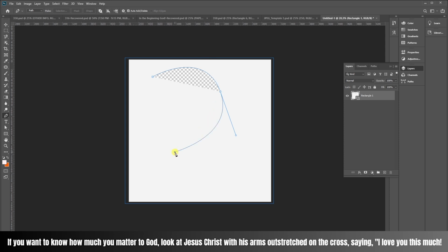Can you see this one is also an arc by default, but in case in the second one I didn't want it to be an arc, what I can do is I press Alt on my keyboard and hold it, and then I click on the previous anchor, and once I click there, it gives me a fresh start. Though it's going to connect, this time it's going to connect as a line. So you take a look at it. Can you see it's a straight line?